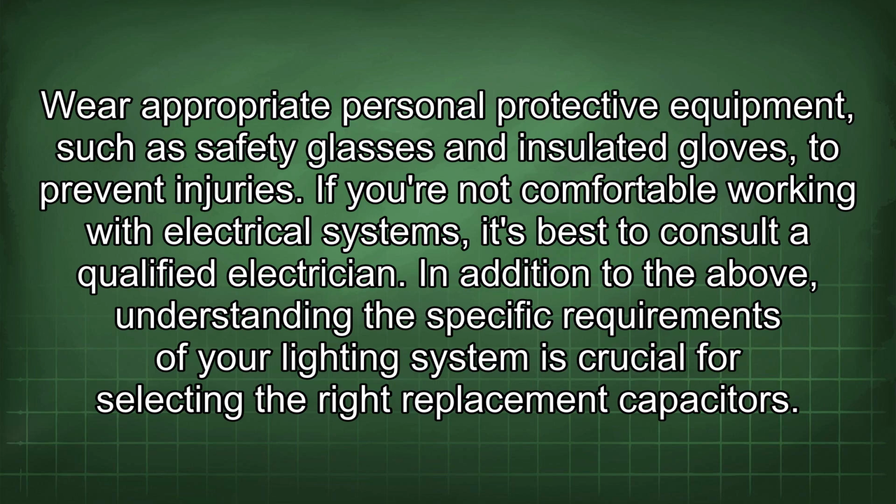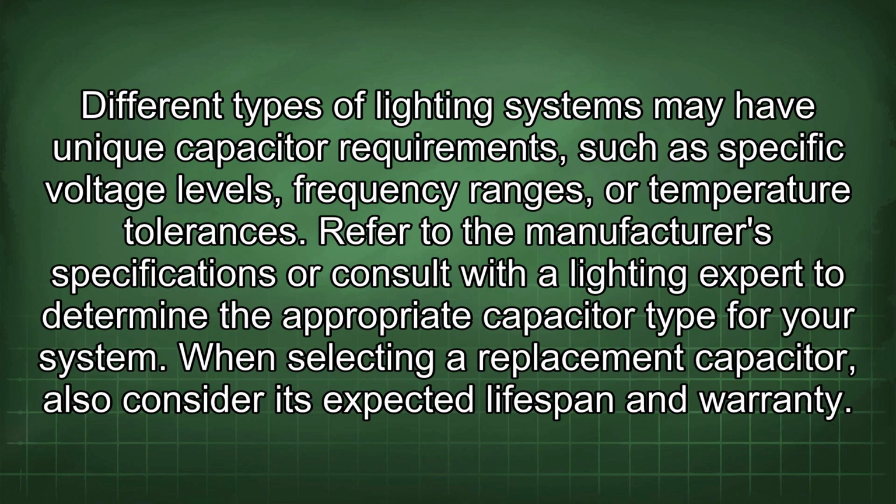In addition to the above, understanding the specific requirements of your lighting system is crucial for selecting the right replacement capacitors. Different types of lighting systems may have unique capacitor requirements such as specific voltage levels, frequency ranges, or temperature tolerances. Refer to the manufacturer's specifications or consult with a lighting expert to determine the appropriate capacitor type for your system.